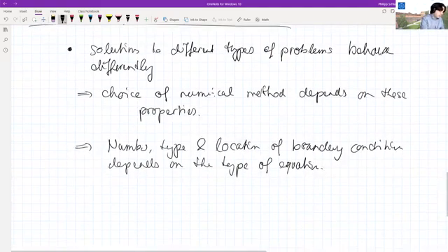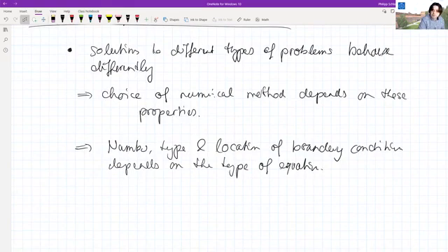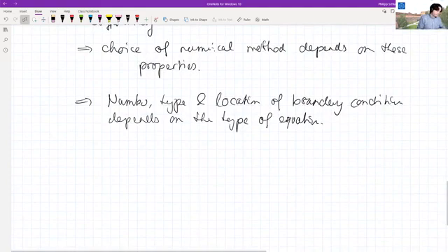Also here, maybe just a brief example, if you have hypersonic flow, typically you would not need an outflow boundary condition because everything is kind of convecting out anyway. On the other hand, if you have a well-behaved, I don't know, a Laplace type of problem where you solve a Laplace or a Poisson equation, of course you need to have boundary conditions everywhere for it to give a correct solution. So therefore, it's very important that we understand what mathematical problem we're actually solving.